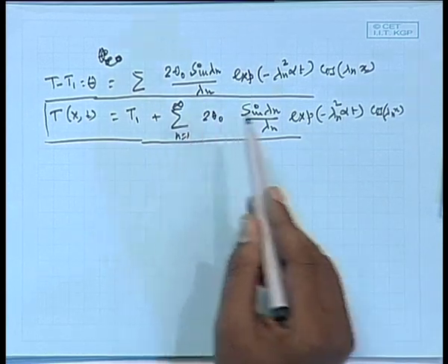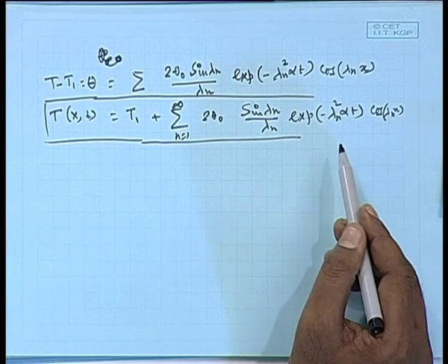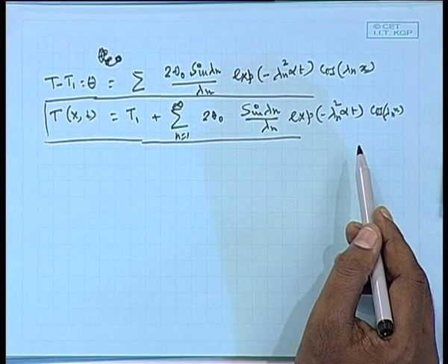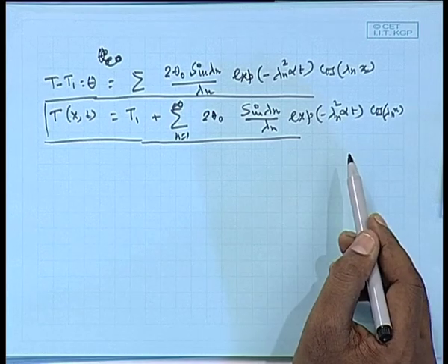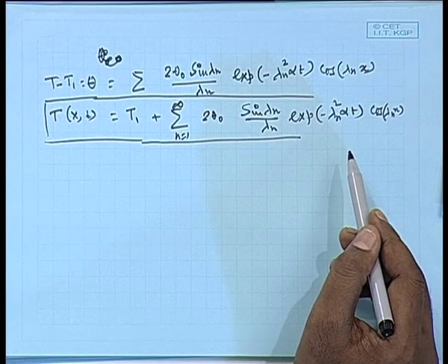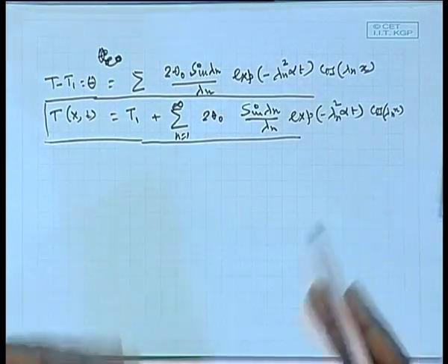Again, as we have discussed earlier, for computing some values only 4-5 terms of this summation will be good enough, because the higher order terms will not contribute much towards the complete solution. Now again, the eigenvalues and eigenfunctions will be changed if you have one mixed boundary condition. Let's say that boundary is open to atmosphere, so whatever heat is conducted at that boundary will be convected away by the forced convection imposed by the external environment.